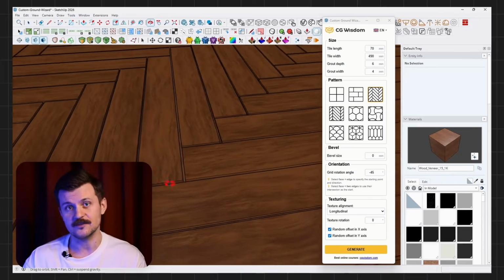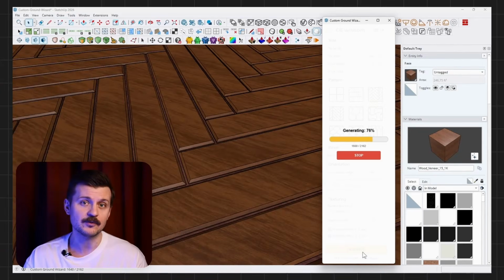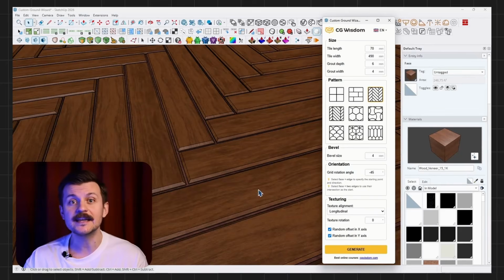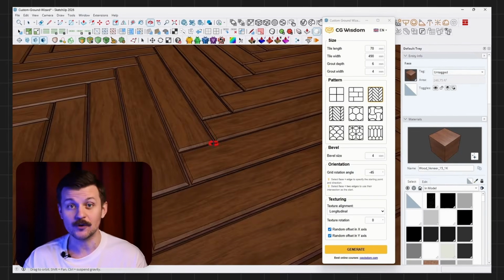Plus beveling. You know well that in reality, no geometry has an edge as sharp as a razor. If you leave sharp edges, the render will look artificial. That's why you set a subtle bevel here, for example, 1 mm. This way, the light in the visualization will break beautifully on the edges of every board. It's a small detail that makes a colossal difference in how your project is perceived.